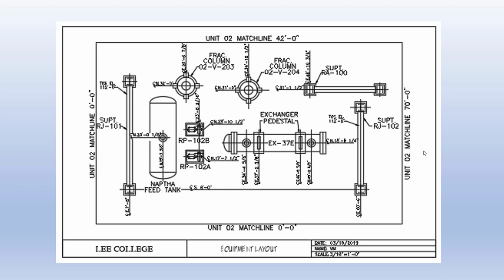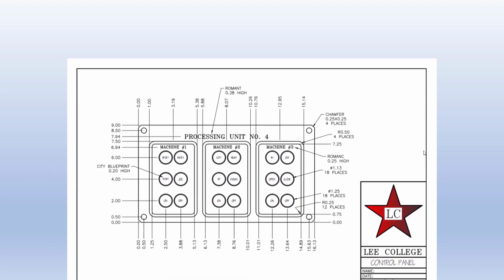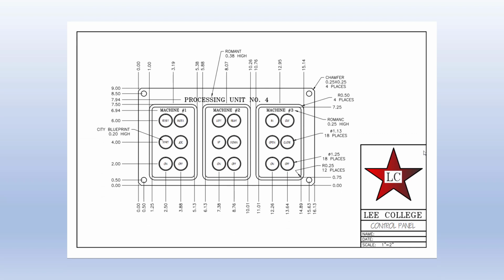It is important to set up the scaling parameters so that when the drawings are plotted or printed, all parts of the drawing are easily understandable, meaning that they are formatted to the correct size according to officially accepted standards for ease of readability and consistency from drawing to drawing. In AutoCAD, the scaling of a drawing will affect the size of the text and other annotation objects such as lines and arrows. When we refer to the scaling of a drawing, we are referring to the plot scale, or what the objects look like when the drawing is plotted or printed out.